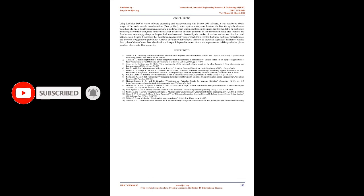In the downstream study area location, the flow became increasingly abrupt as the pier thickness increased, observed by the number of vortices and vector directions, until hitting against the pier. It is evident that the relationship is directly proportional: the bigger the thickness, the bigger the turbulence, and therefore a bigger scour probability. Analysis of variance for each pier indicates an important significant difference, which is also visible from the water flow visualization in the images. Hence the importance of building a pier as slender as possible, where water flow passes by.